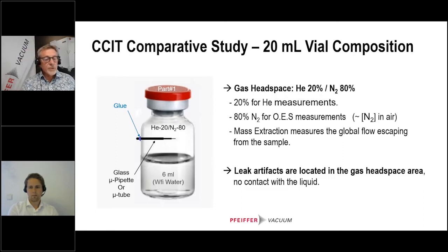We have decided to fill the vial with 6 ml of WFI water, and to leave gas headspace around the defect. We did not immerse the defect inside the liquid. So we take care to have no contact between the defect and the liquid during this study.